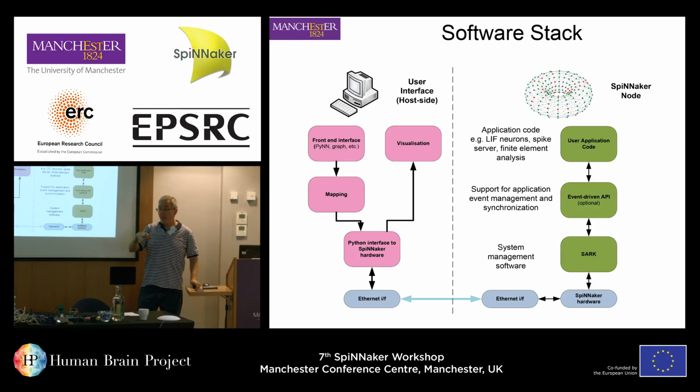Now, if a core is running some neurons, it'll be an executable dedicated to running LIF or exponential or whatever the neuron type is. But we have other executables that also run. Some cores are responsible for gathering information. We have packet gatherers that take messages and convert them into formats that can be sent back to the host. What do the other executables do? I'm trying to think what the other ones do. Other cores, what are they doing? There's packet gathering, there's the neuron models, the re-injector, that's the other one I was thinking. Yeah, so that'll do.